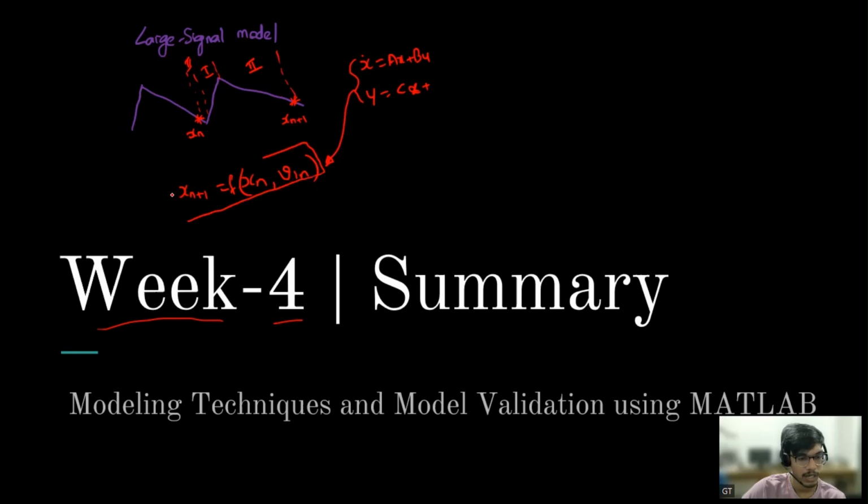So why are we going for the large signal model? Because in the case of discrete time, we don't have the complete information, right? We only have the particular sample information. So if I know the sample information here, can I get the next sample? Yes, when you know the input and the present xn sample, we are trying to get xn plus 1. So this is a model which will give the information about the samples xn, where xn is iL and vC, that is, iL at the nth instant and vC at the nth instant. So we are getting the information about the system state variables, everything.